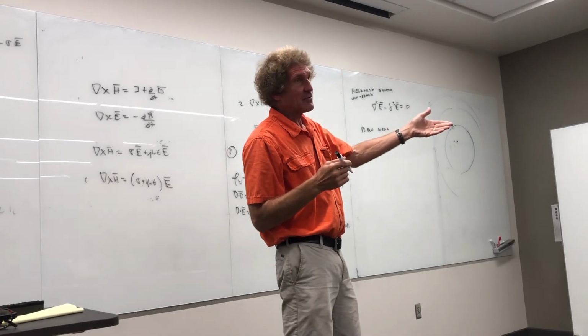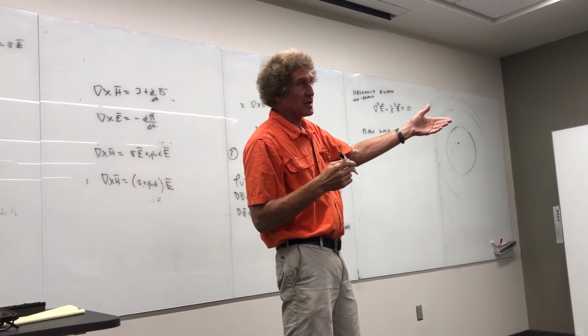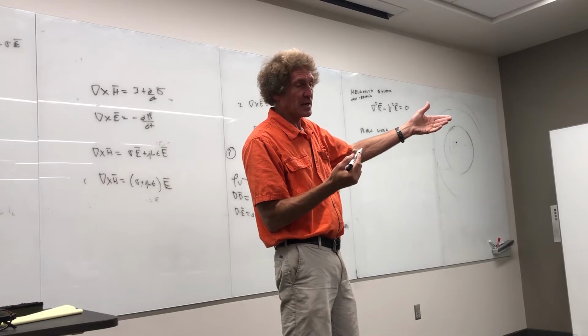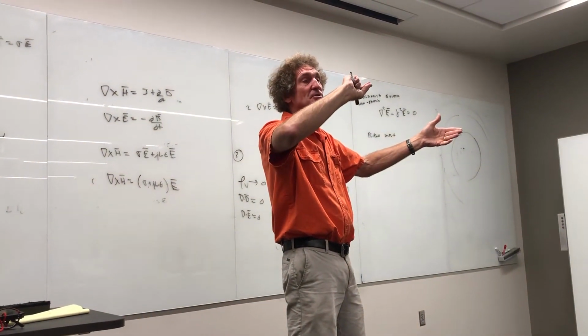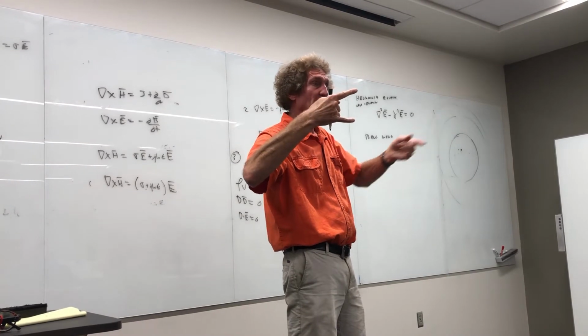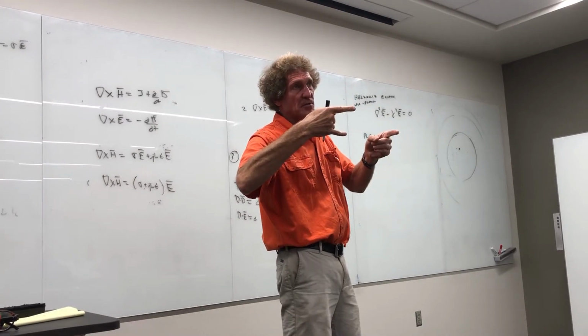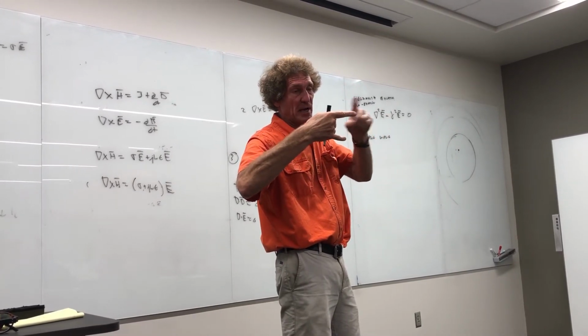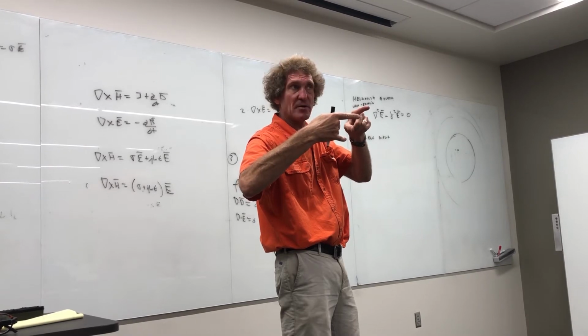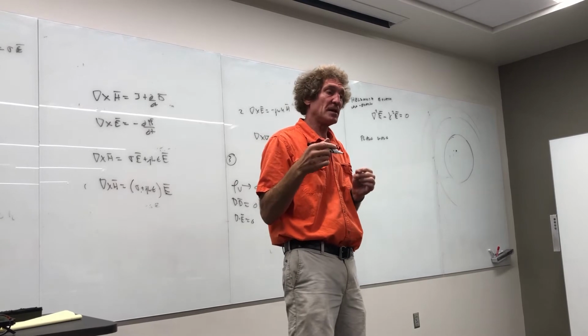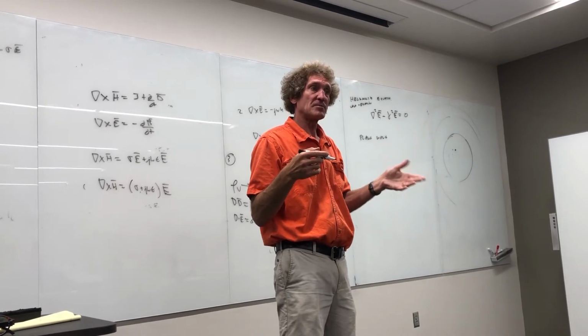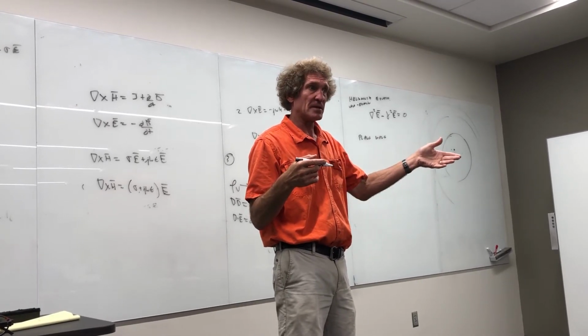Similarly, the magnetic field around an inductor is tied to the current creating it. If you take an inductor with a large current going through it, and you take a resistor and just stick it right across there, all that magnetic energy will basically cause current to pass through the resistor. You'll get I squared times R heating, and the integral of I squared R through that resistor dt would be the total amount of energy in the inductor, 1/2 Li squared.